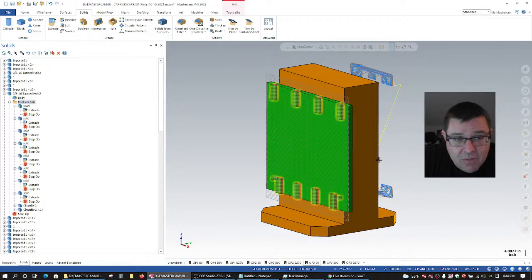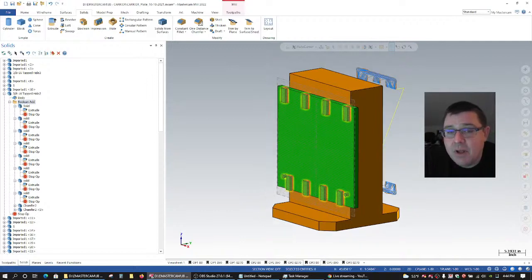If you're searching for something, if you're turning a level on or turning a level off or doing something like that, there's a lot of operations where it's not just going to that one piece of data and manipulating that one piece of data in the database. It has to parse through the whole database. So things like turning stuff on and turning stuff off for the display list. A lot of these operations, it's like it has to iterate through the whole database before you get results. So I wouldn't say that's true with everything, but certainly as your files start to get really bloated, they start to get above, kind of 100 megabytes, that can definitely slow you down.